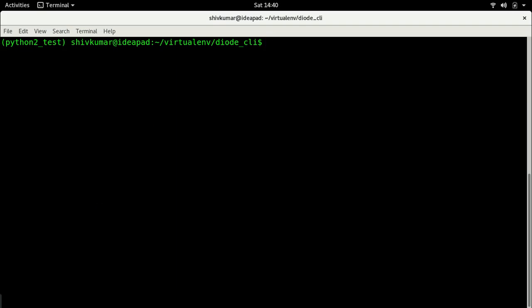So now the way to start this simulation is you got to say Python circuit solver. Circuit solver is the main file which launches the circuit simulation. All right. In Django you would do python manage.py run server. Here you do python circuit solver.py. That's all you do. This is basically like saying run or pressing the run button in a simulator.